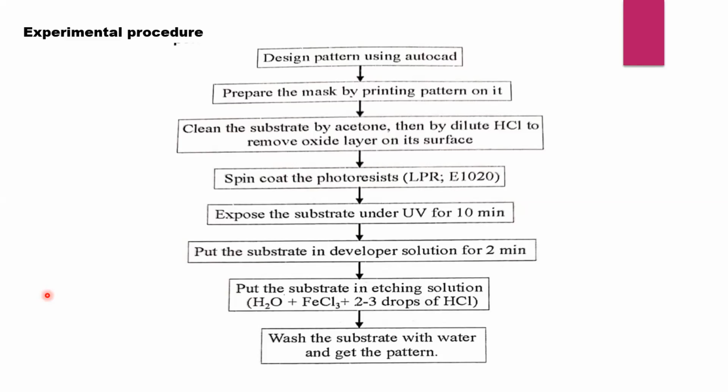Now, dear students, just think, is our job finished with this? No, it is not finished. Yet to be done something. No doubt the pattern has been developed on the surface of the silicon substrate, but the photoresist molecules are there on the surface of our product.